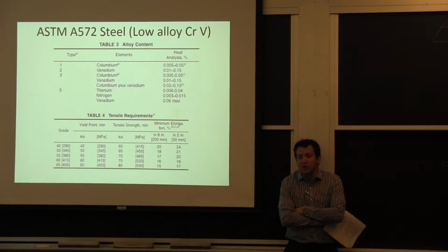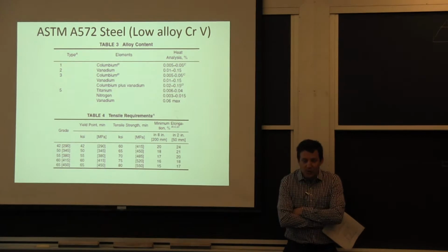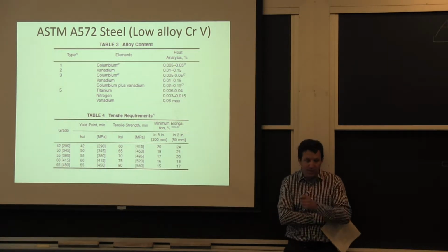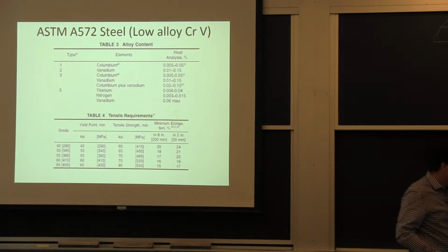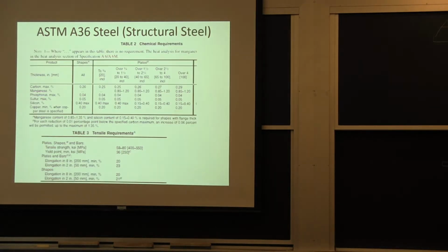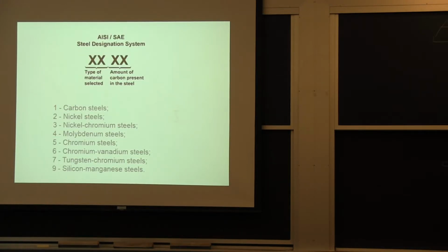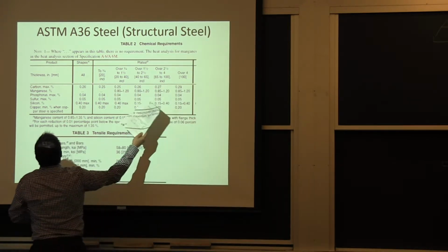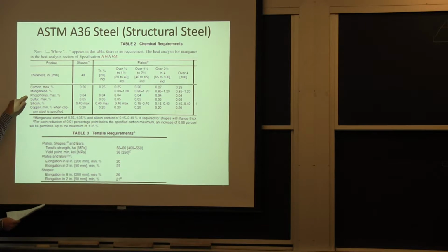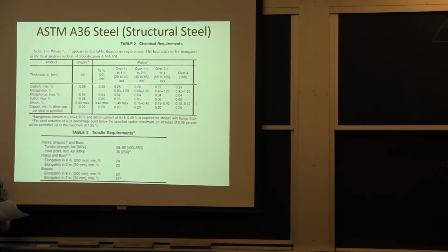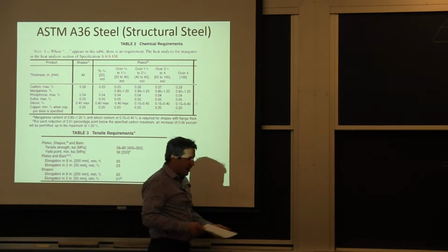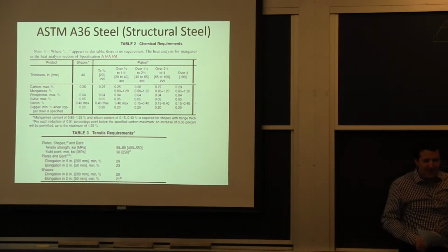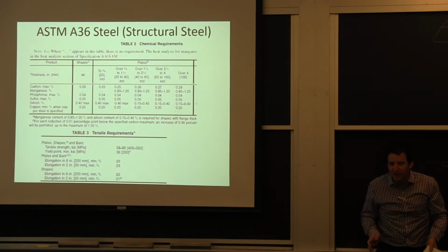The first thing I would always ask is a chemical analysis. Because otherwise it could be anything. It could be high-strength steel that you can't weld. So this idea of getting at least one number of the chemistry was typically the way I was treating this. I was going back to the ASTM here, and I was able to say, okay, for the shape I have, do I meet the sulfur, phosphorus, manganese, and silicon requirements? And if I did, I loved having some indication that my material properties were okay. But that's not easy.